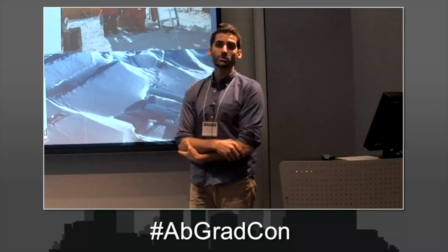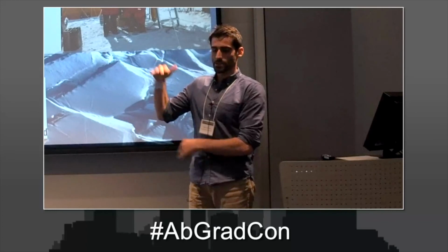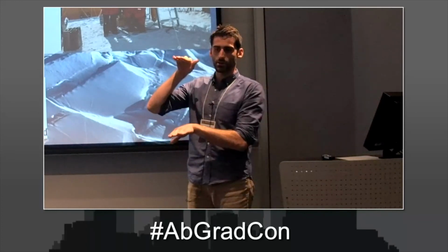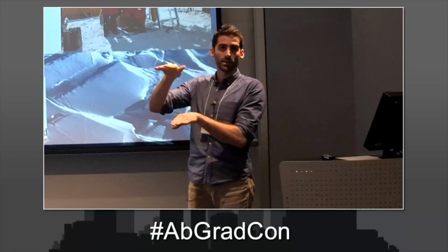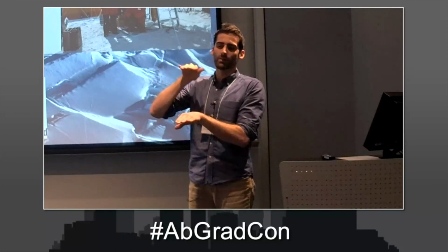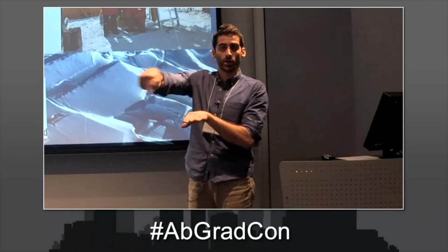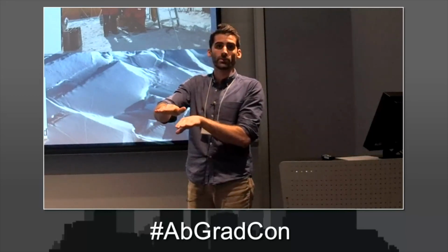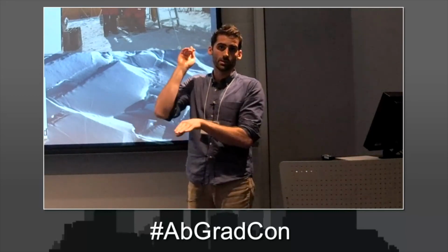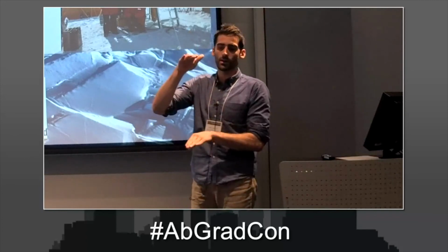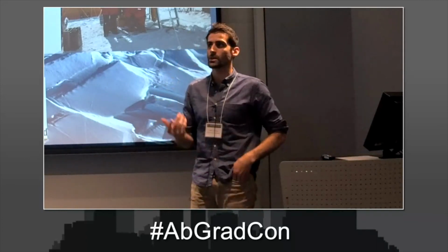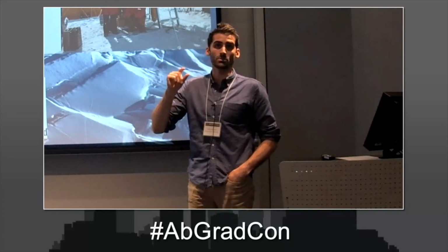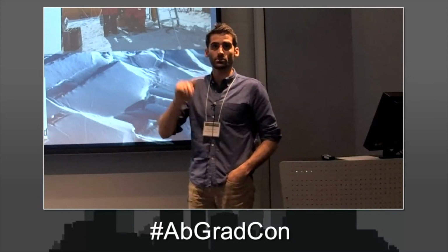So what we're doing with the underwater vehicles is basically mirroring the flight. So the Reason instrument, again, they use Antarctica as an analog. They would do overflights and get a radar profile of the ice and the ice shelf from above. And then we try to match that radar profile with the vehicle from underneath and use our sonars to look up and get the thickness and the composition and the overall texture of the ice from below and use it as a kind of ground truth for the radar.